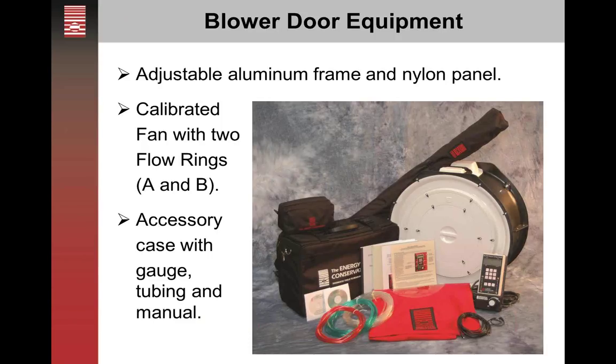Blower door equipment. This is certainly the offering that we have from the Energy Conservatory, but certainly any manufacturer that creates or sells blower door equipment is going to have very similar equipment. We have a blower door fan, a door frame, some form of gauge for reading the value, and a case to hold all of the various accessories.